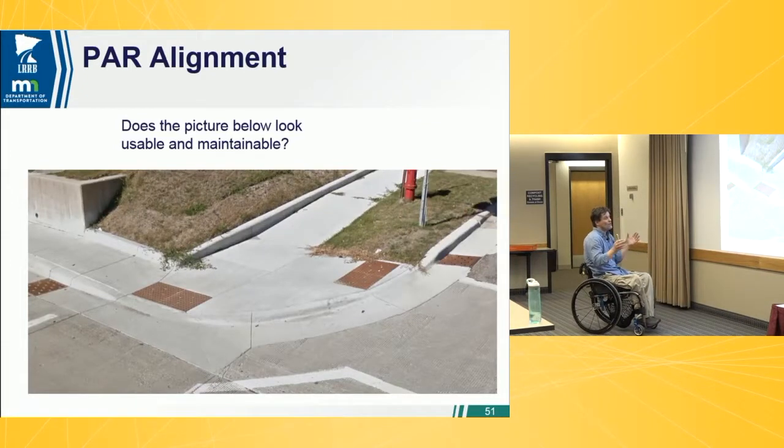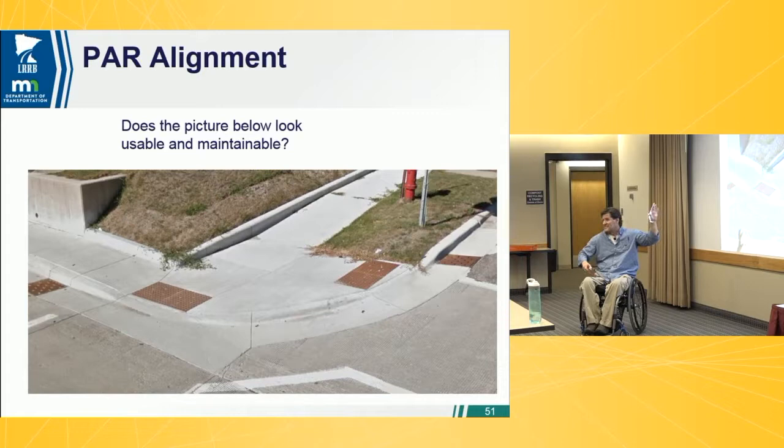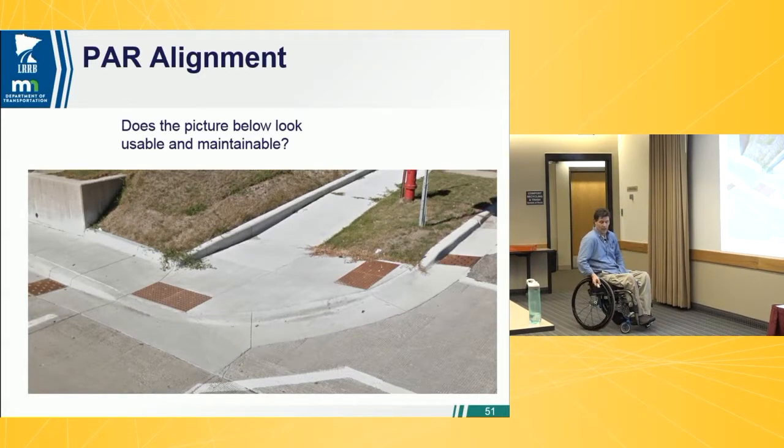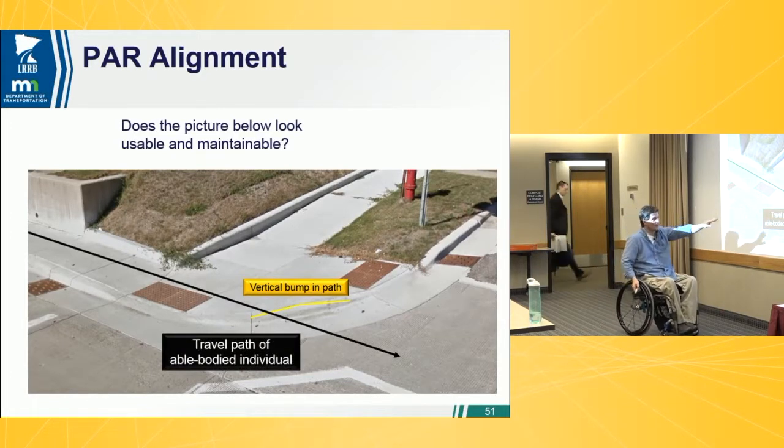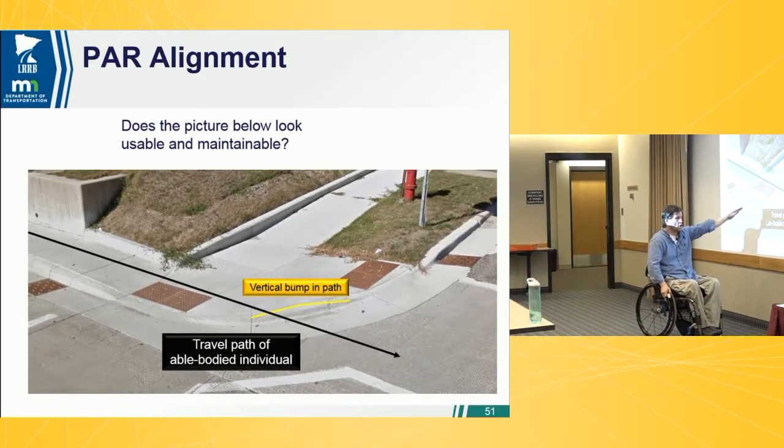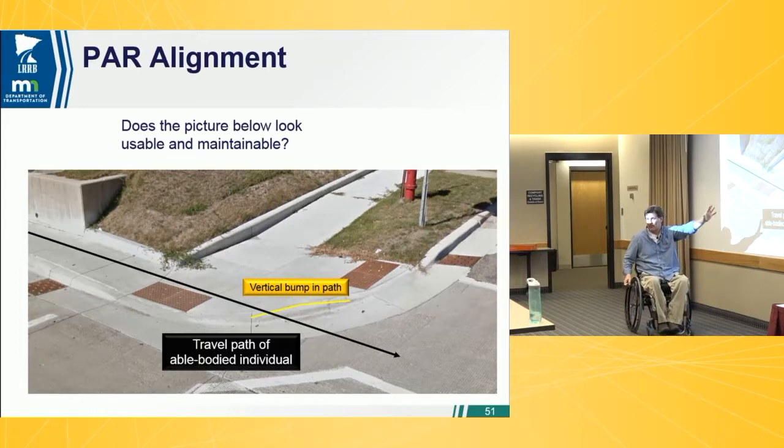Here is one. This was done quite a few years ago, and we were always saying that 2 ramps are better because a visually impaired user can get that distinction between crosswalks and everything. But here, this definitely did not work out. Call this the square peg in the round hole, because we've got a 5-foot sidewalk coming in here, this big fill area, this hill behind us, and the curb line wasn't changing. So for people walking straight along in this direction of travel, you've got this curb bump in the middle that can be a trip hazard.